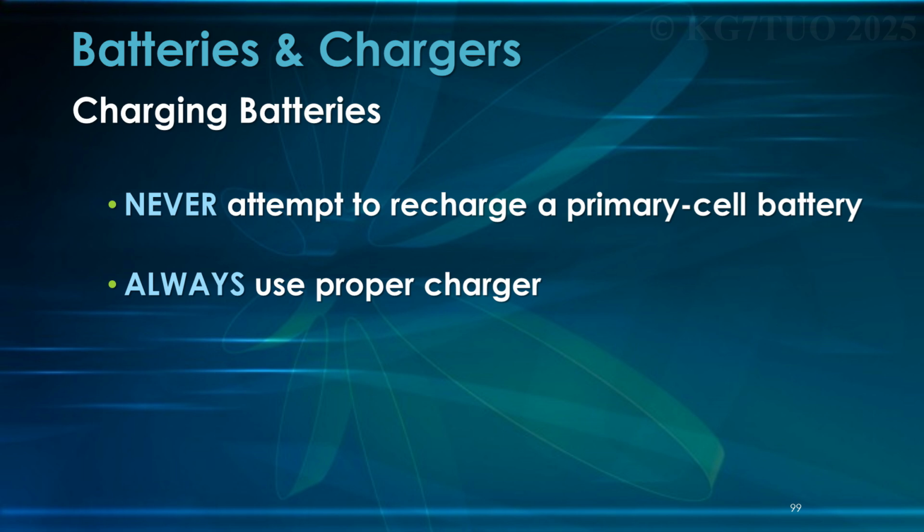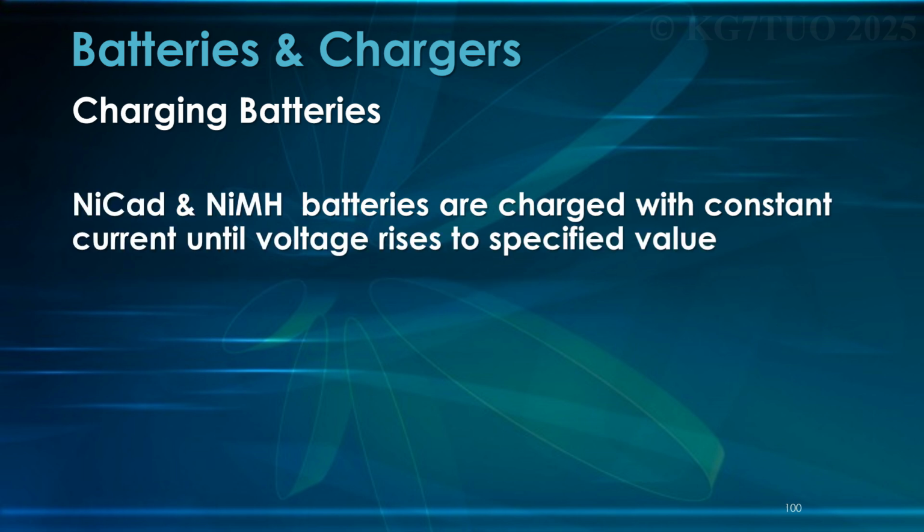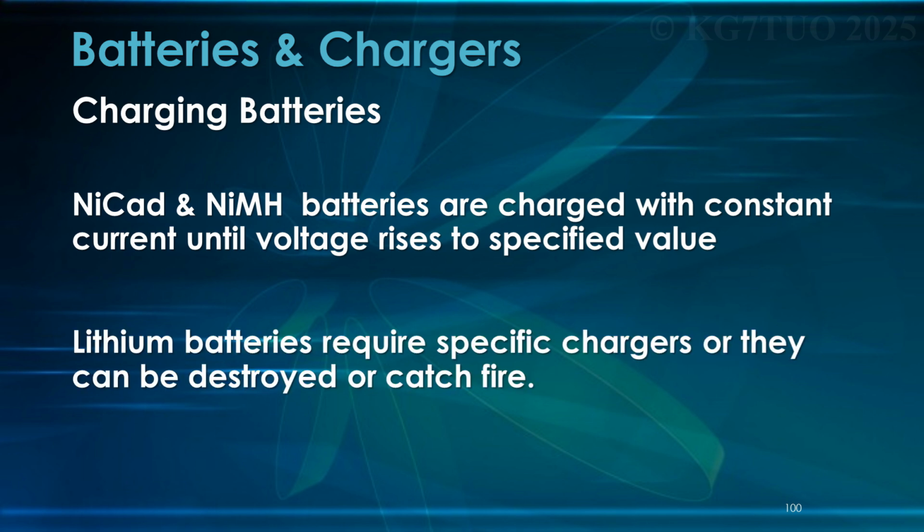Always use proper chargers. NiCad and nickel metal hydride batteries are charged with a constant current until the voltage rises to a specified value. Basically they have different charge curves, and you'll want a charger that matches the charge curve of the battery.